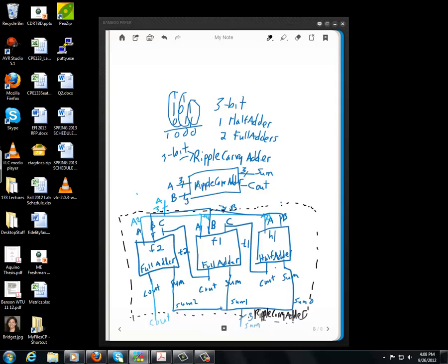And as you can see, the ripple carry adder has the same outputs, Cout and sum, and A and B as the inputs as my overall black box diagram. So here basically what I did was I drew the overall black box diagram and then I expanded it out to show the inner components and how they all connect together. Alright, so like I said, it's very important that your names all match with these diagrams and your code so you don't get things all messed up. So now I'm going to show you how to write this all up in code.